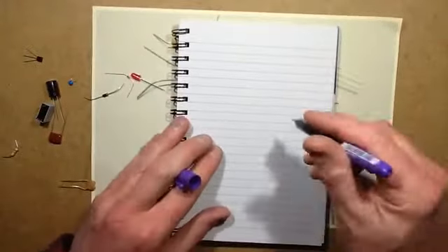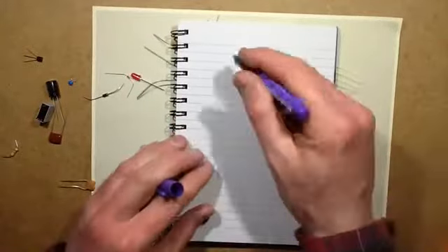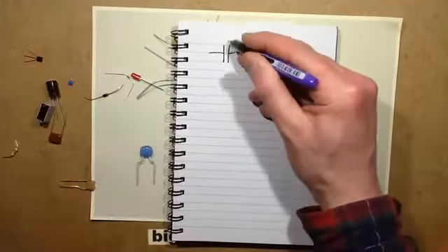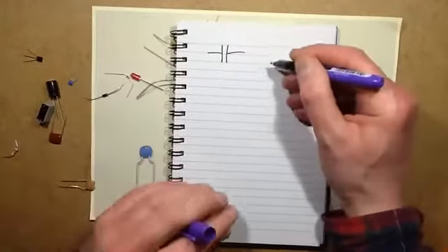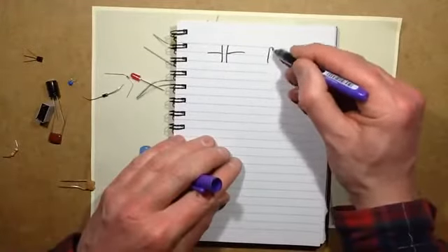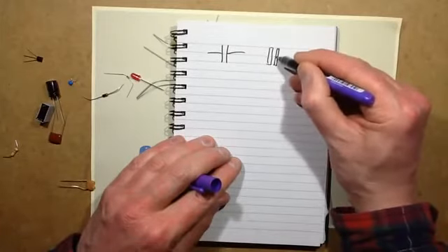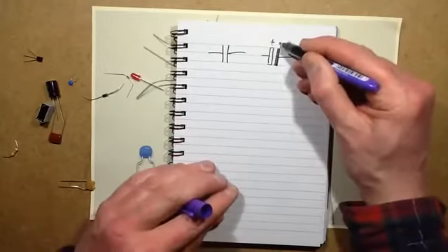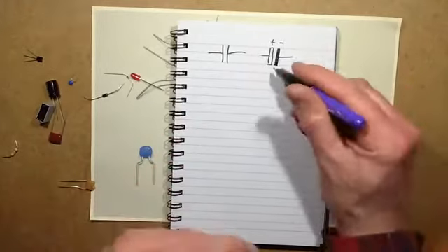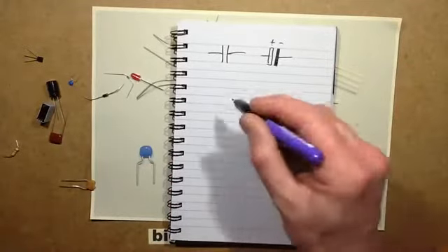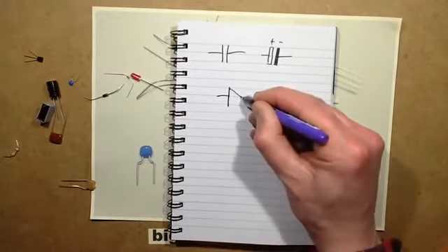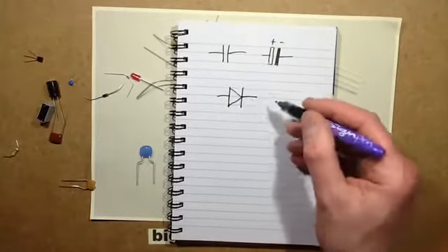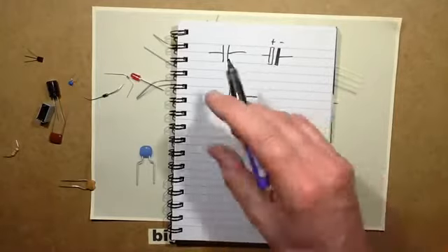So the symbol for a diode, I didn't mention the symbol for a capacitor was that, basically representing the two metal plates with a sort of air gap in between. And in the case of the electrolytic, the positive and negative are marked, with positive being the empty box and the negative being the filled box, just for polarity reference. However, moving on to the diodes, the symbol for a diode is very easy. It's very self-explanatory. In the water equivalence thing, it would be a pipe with a one-way valve in it, so the water could only flow one way.